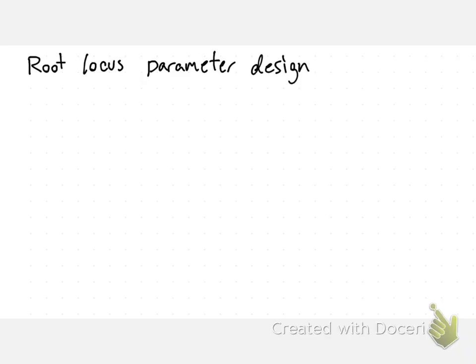So what that means, if we're trying to affect where our poles are, we don't need to have a fancy control system with a sensor and a meter. We can use the root locus math to determine what size mass we would want in a mass spring damper system, or to determine how large of a damper we'd need, or what size vat we would need in a fluid system, and see the effect on our poles of changing a given parameter.